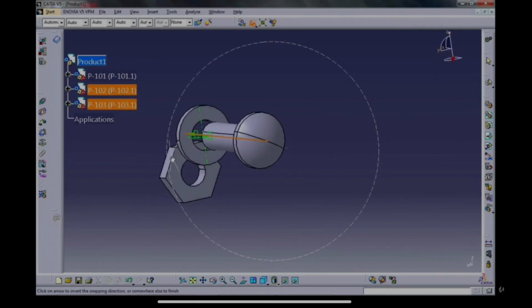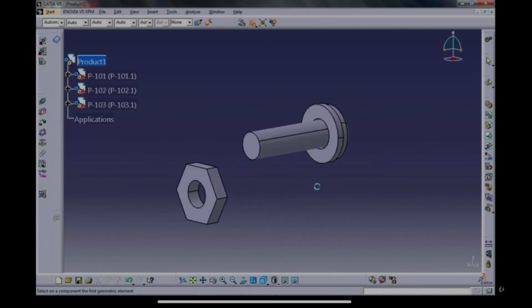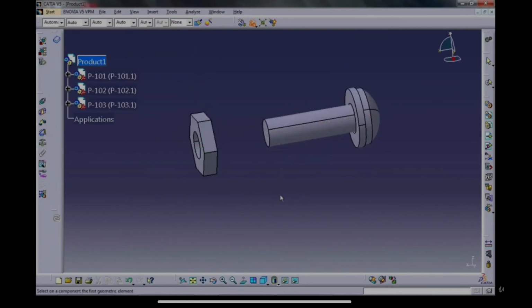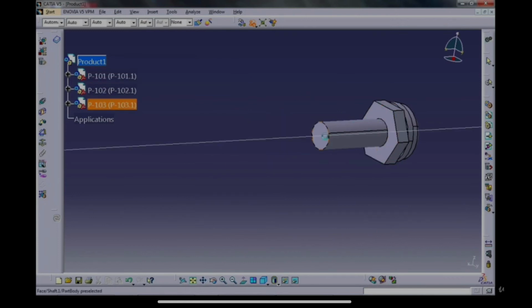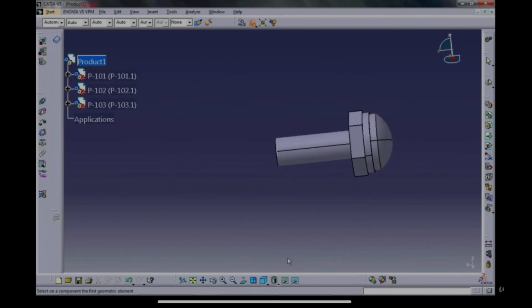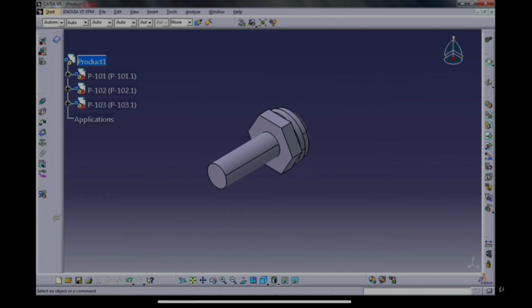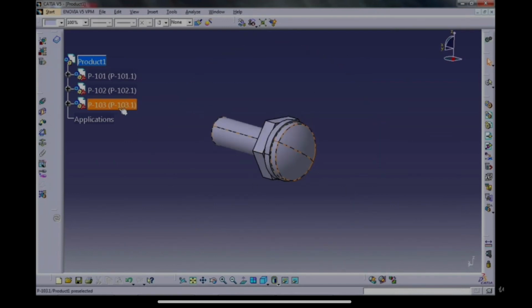I will check on the object that we have made. What we require is that we must have made some cuts over there. So again we'll go to the part which we made before. Here we can do the editing if required. I'll make one rectangle, which will cut through it. If I take the pad command, it will directly